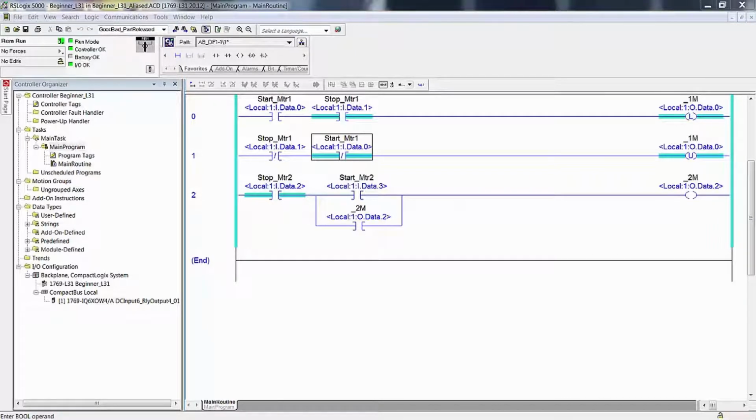We want a system start and a system stop push button. That could sound like one push button, but we want a system start push button and a system stop push button that enables the conveyors to run, enable only, not run, enables them to run, or disables them from running. This does not actually start and stop the conveyors directly, just enables or disables their ability to start. Following a system stop, we do not want the conveyors to be running with a subsequent system start, regardless of their state when the system stop occurred.